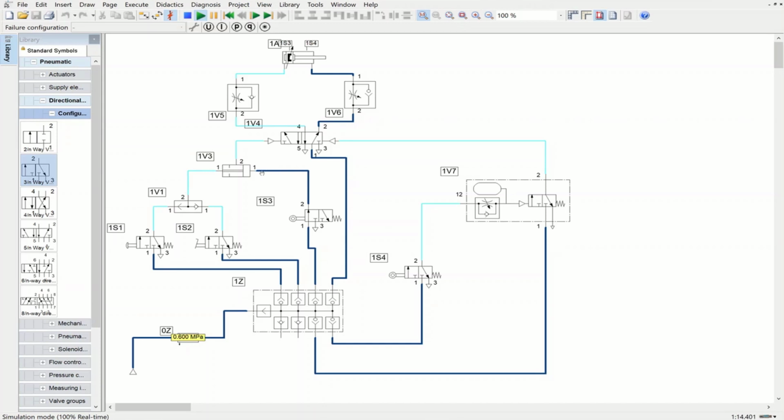One inlet is already in the through condition, and the other side will be through. Then air will pass, and from there you would have actuation shifting to the second position. Air will pass through this throttle check valve, getting to this double acting cylinder. And with these two throttle check valves in here, we have the capability of adjusting the speed of the piston. So let's start again.